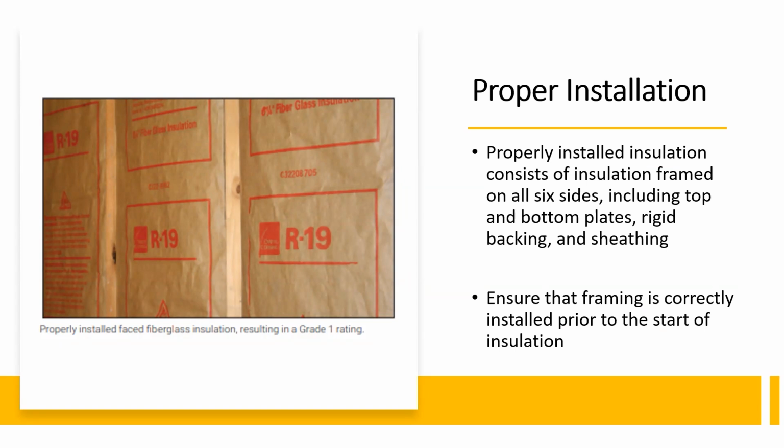So we actually have a question on here. How can a balcony be properly insulated? That can be determined differently. Is there a conditioned space above or below the balcony? If so, it needs to be like what we just saw with the cantilever. It needs to be insulating whichever side is the conditioned side. It needs to be in permanent contact with that conditioned side.